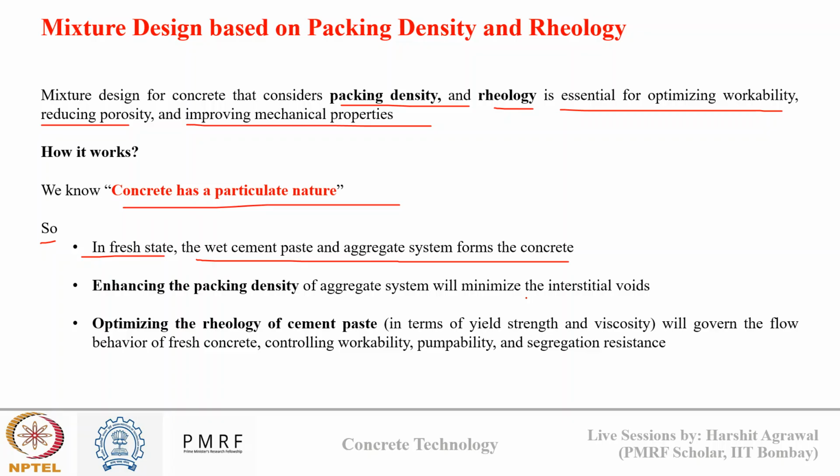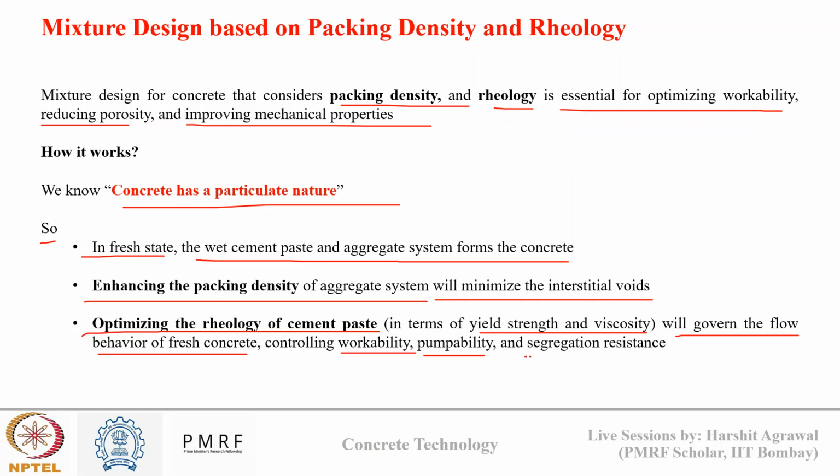Now, for enhancing both strength and workability, we will enhance the packing density of the aggregate system, which will minimize the interstitial voids. And then by optimizing the rheology of the cement paste in terms of yield strength and viscosity, we can optimize the flow behavior of fresh concrete, which will control the workability, pumpability, and segregation resistance. Therefore, in this way, we are optimizing both strength and workability of a concrete.